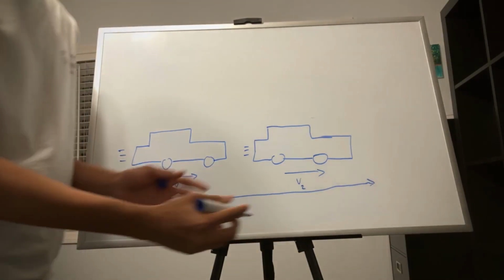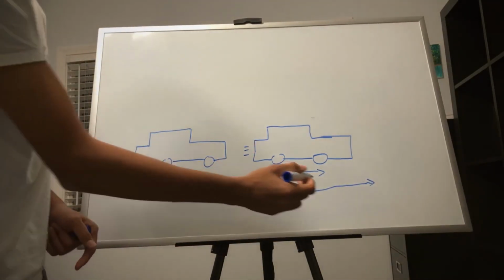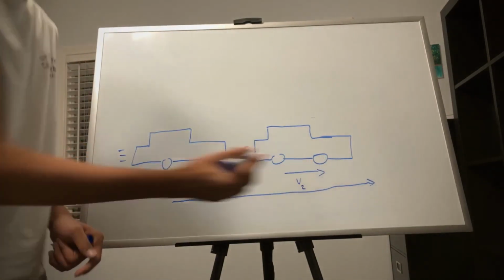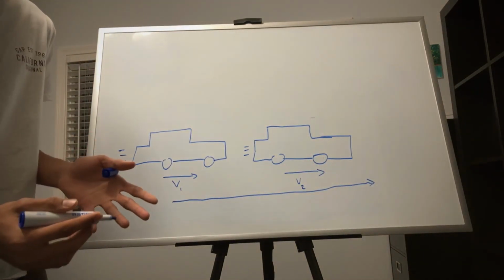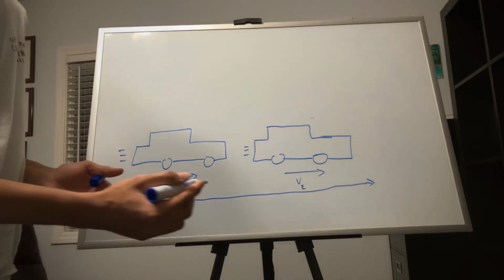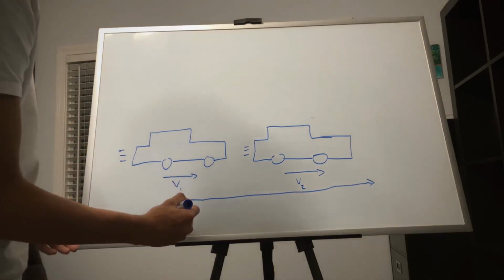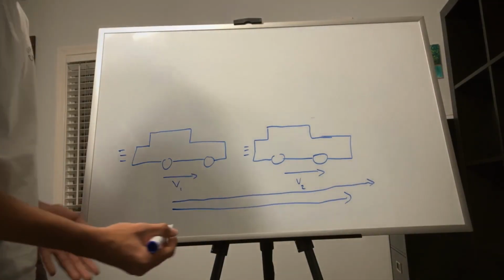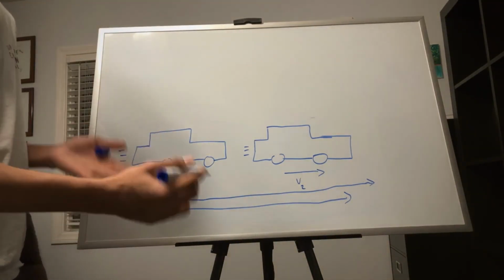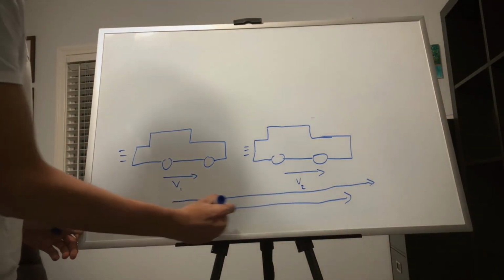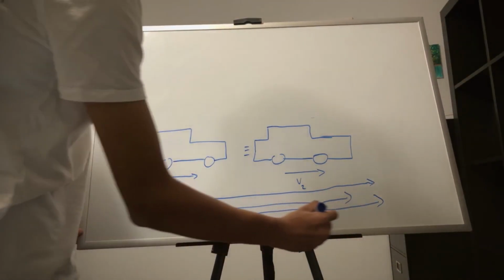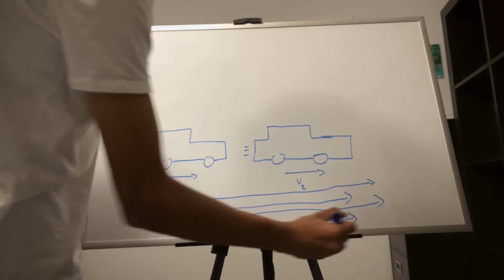So we're going to start driving faster than the car. Since our position is going to be past the second car, our error becomes negative, meaning our output becomes negative. So we're going to slow down the car a little bit. And what happens is what we've seen before, where a proportional controller, in a lot of cases, ends up in this oscillating motion, where we never really eliminate the error.